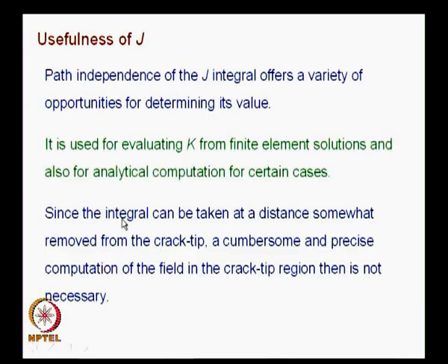Since the integral can be taken at a distance somewhat removed from the crack tip, a cumbersome and precise computation of the field in the crack tip region then is not necessary. See, if you take a benchmark problem and apply J integral, you are not going to have any advantage, because for benchmark problems you can really fill it with very refined mesh.